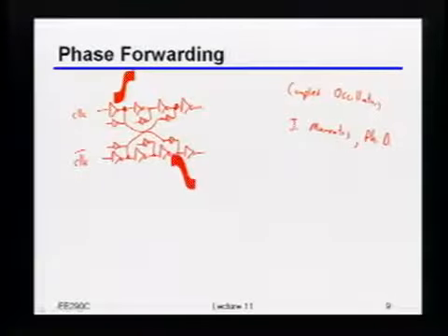Okay? So basically what he showed was that if you took a whole bunch of different ring oscillators and coupled them in smart ways, you could essentially guarantee certain modes of overall oscillation, but get the equivalent of gate delays much, much less than a fan out of 4. Or really much, much less than what you could have done without these coupling tricks. Okay? So if I remember correctly, he was working back in maybe even half micron technology, and he was getting things in the 10-ish picoseconds of delay, or I should say phase resolution. Maybe even less.